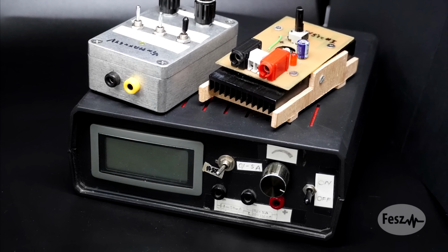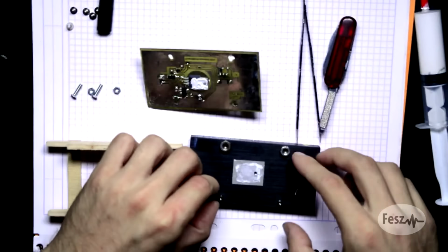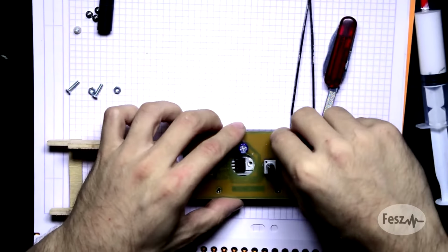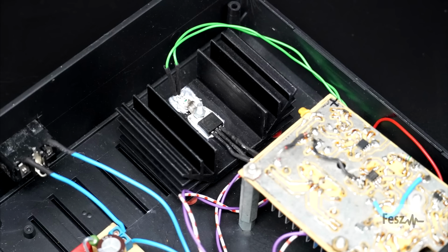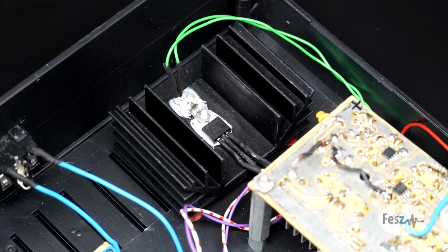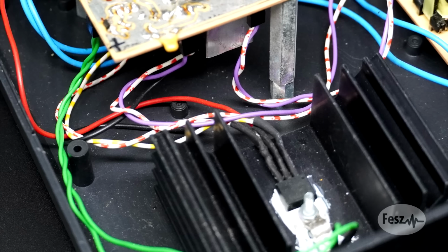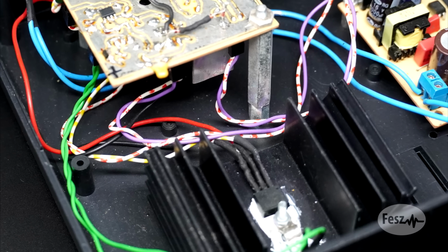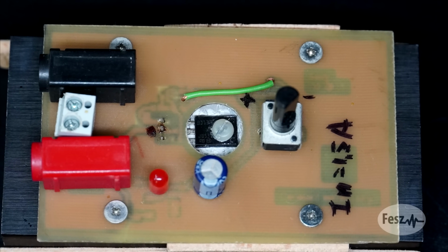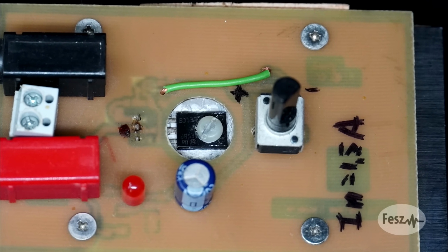Now, the last thing to mention about this design is that I wanted to build it a bit differently from my previous active loads. So I did build active loads in the past, usually current loads. I also covered one of these in more detail in an older video. But the main difference between those and today's build has to do with how the power transistor is cooled. So the typical way to go about this is to have some sort of through-hole large power transistor screwed onto a heatsink. You either connect this to the main board with wires, or you need to make sure that the holes in between the board, heatsink, and transistor are all aligned.